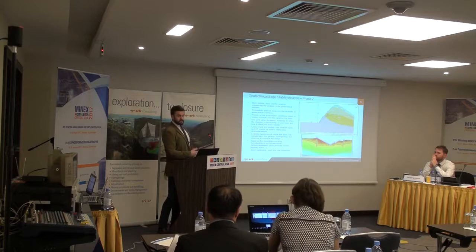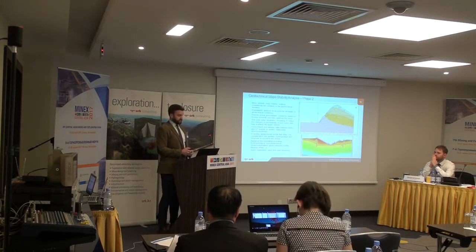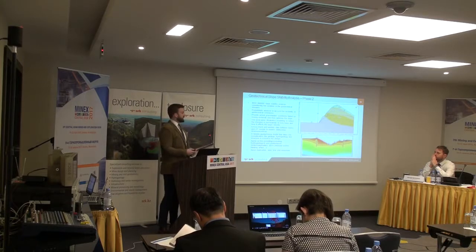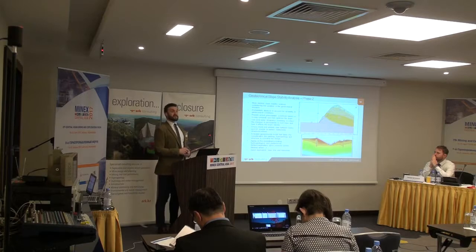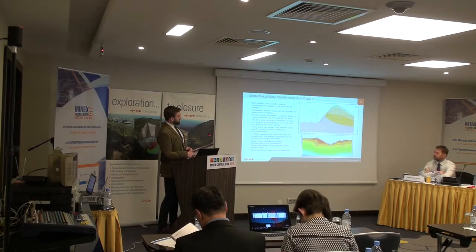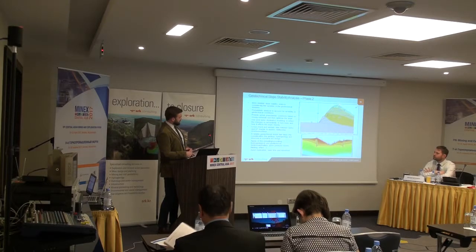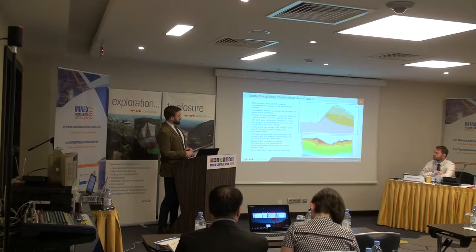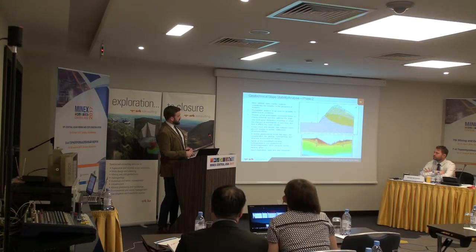And it's really only then, after we've done the detailed numerical modelling of the hydrogeological conditions, that we can do a more detailed slope stability analysis. What we see here is a detailed slope stability analysis containing different rock mass domains. We have different groundwater levels. So we have an average groundwater level, a low, or best case, and worst case.